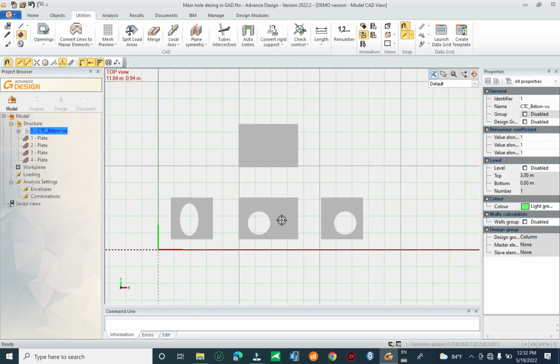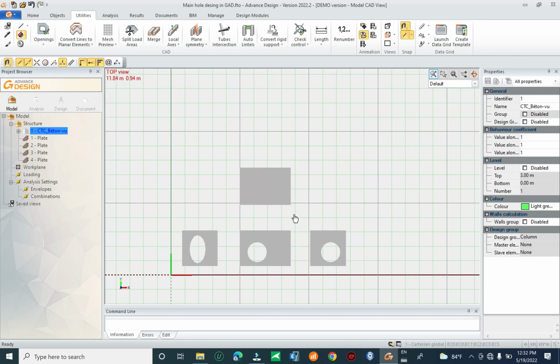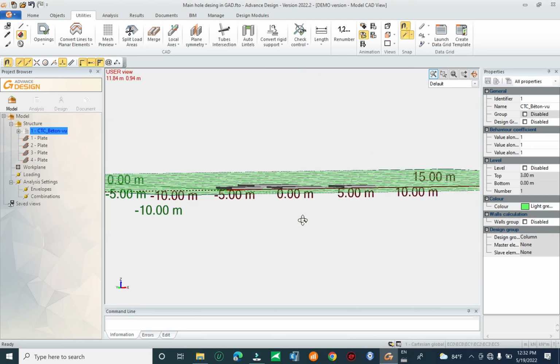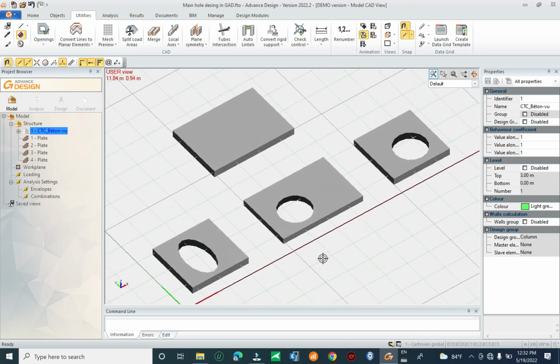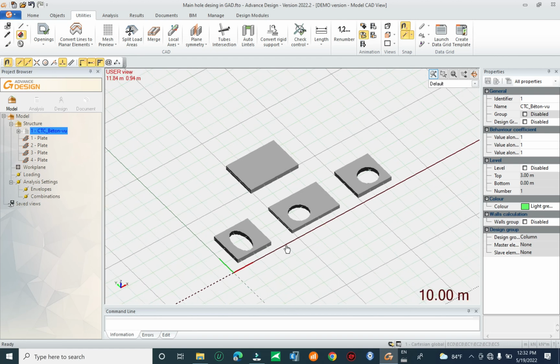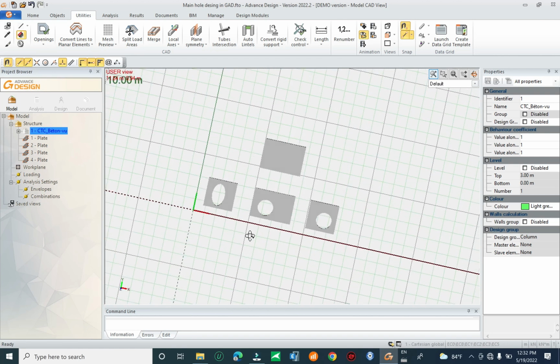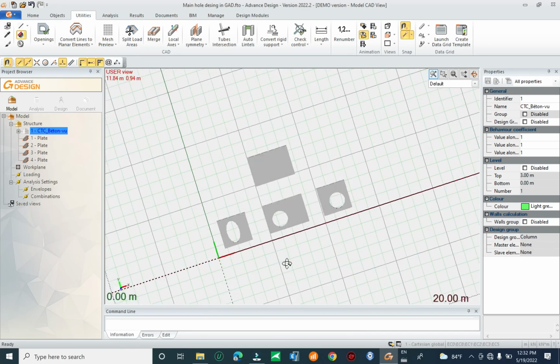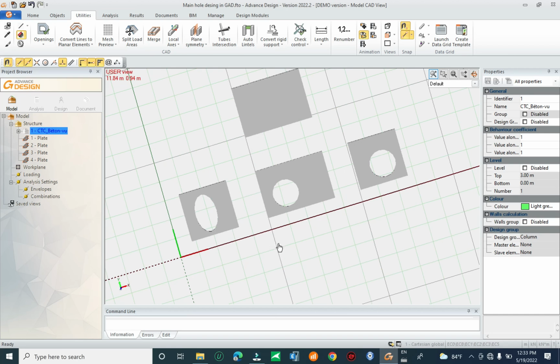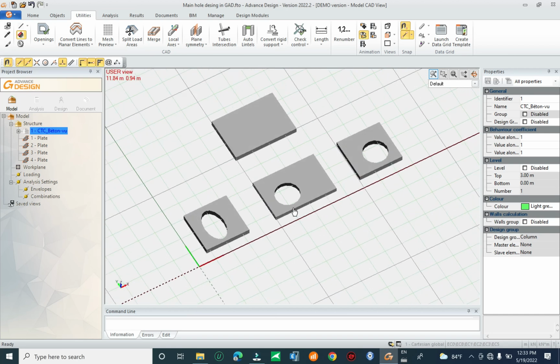And now let's check for the... now you can rotate it. Okay, this one you can rotate it. Press C and right click, and you can rotate the view. Now you see here your view in the top view. You have to rotate the wall to the vertical.